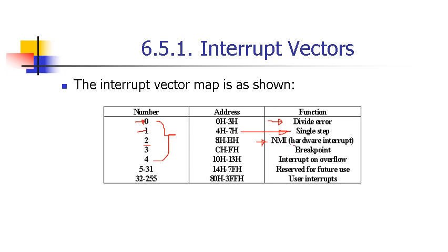In hardware interrupts, we have a maskable interrupt, an interrupt service routine that can be rejected or can wait, and a non-maskable interrupt, an interrupt service routine that has to be called and run immediately.